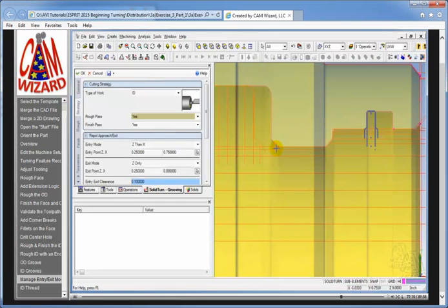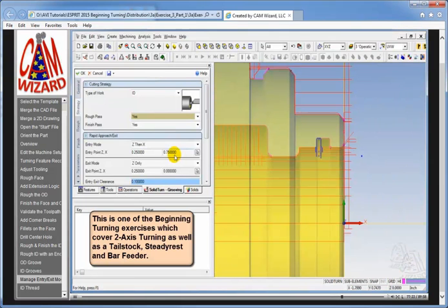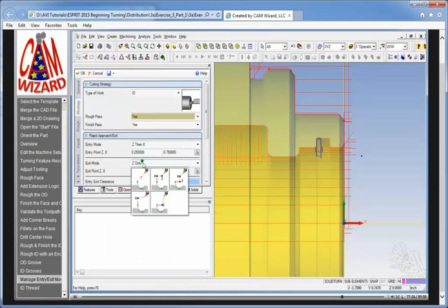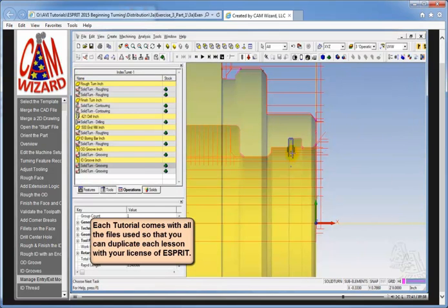So when I'm done with this operation, I can make it pull down to a diameter that's outside of this area. Put my cursor down here, I see that number is about 660. So if I drop down to about 650, something like that, I might drop in where it says exit mode and say, let's go to X only of a value of 0.65 or 16.5 millimeters. So we go about 16.5 millimeters down. Now what that does, if I hit OK, is create a point right there. So when the operation is finished, it's going to wrap it to here.